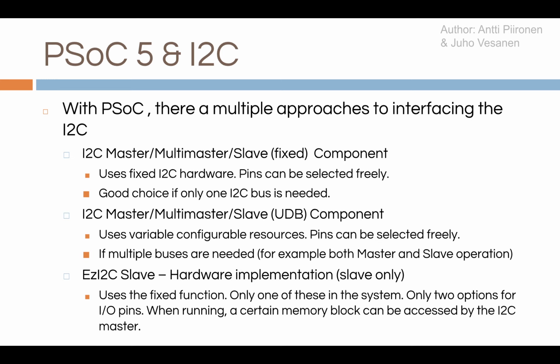If you have multiple needs for I2C buses, then I would go with the UDB component, but anyways, it works the same. It just takes these UDB resources.